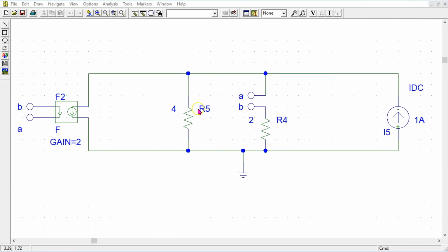This is the given circuit of interest simulated in PSpice. Here we have chosen to apply a test current source. For a test current source, the current IT must be flowing into the terminals of interest. Here, IT has a value 1 amp, and we need to find the voltage VT.